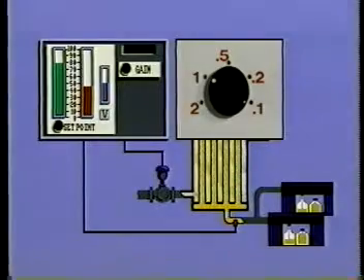To get this performance, the engineers found that a gain setting of 1 was required. When the gain was higher than 1, the process cycled at temperature extremes nearly as great as those with the on-off controller. On the other hand, when the gain was set lower than 1, the control action was sluggish, and a large amount of product was lost during startup. Experience indicated that there was an optimum gain setting for this type of process. Nevertheless, there were more troubles just around the corner.